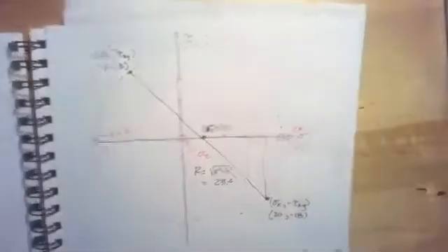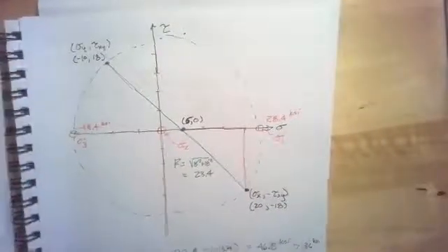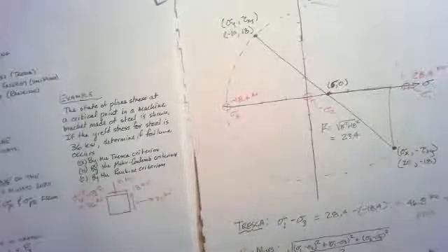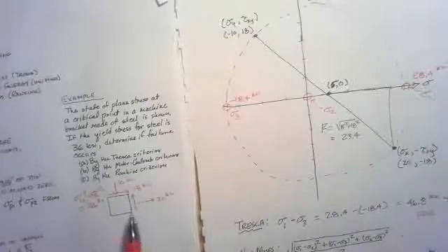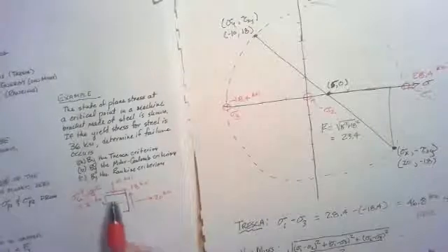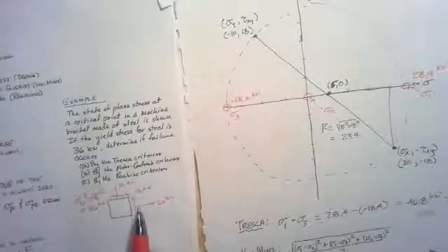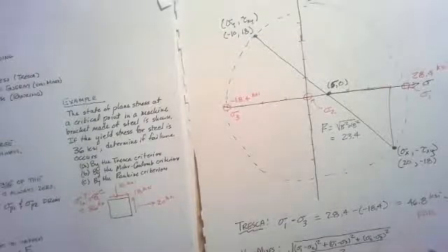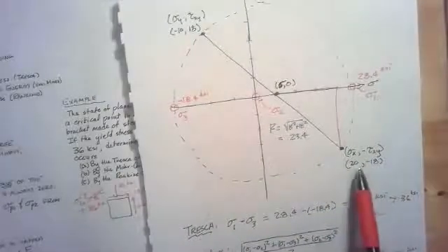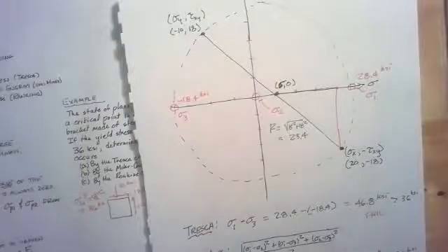Well, if I wanted to deal with this problem, I would want to work with Mohr's circle. So for my element, I have sigma x of 20 KSI and tau xy of 18 KSI. Of course, on the original element, this is positive 18. But for drawing Mohr's circle for the x point, this is negative 18. So I would want to find the point 20, negative 18.